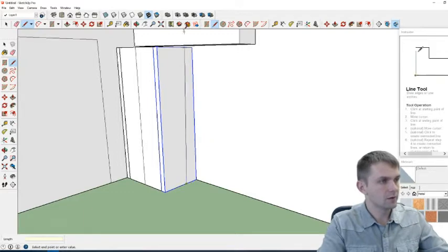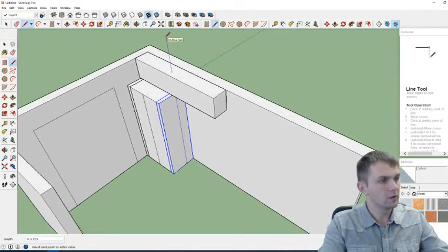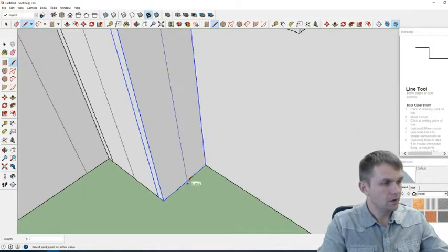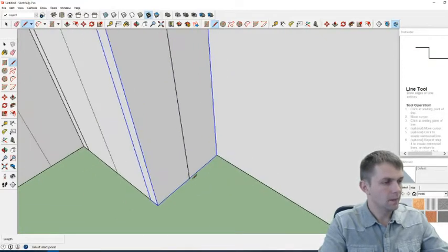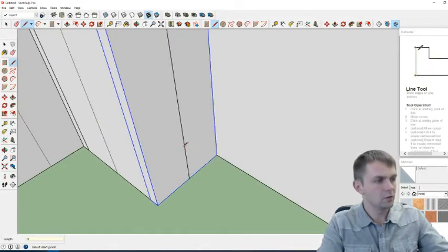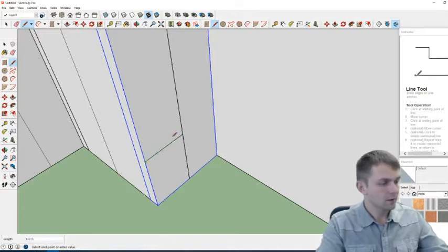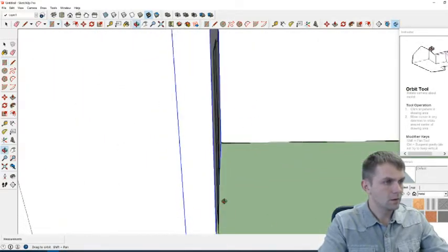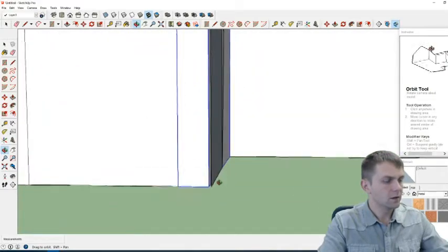Now let's say we make a 16-inch bench, and then see how I can, with orbit, go straight up to see where the bench is gonna end. The bench is usually 18 to 22 inches tall, so it's pretty much the same as your chair. See how there are so many lines, so something is not lining up in here.